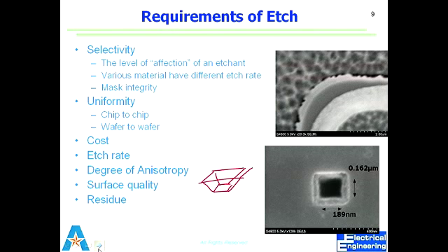But we see that the lower material has been etched, gives you a very non-uniform field. So that tells us that this is not uniform. If it does something like that, it would be very variable on different dies. So there is no uniformity. We want uniformity of etch from one chip to the other chip, from one wafer to the other wafer. On one wafer, we have different dies. It should be the same all over, and from one wafer to the other. It's not an easy job. Once we get there, we'll see why.